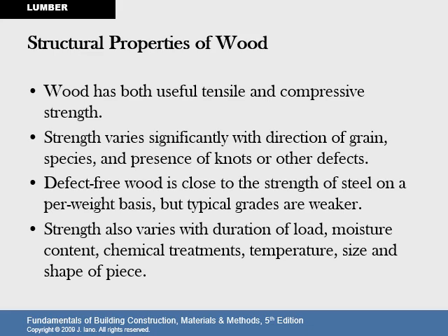Structural properties of wood. As you know, we're making wood studs, so wood has both useful tensile and compressive strength. The strength varies significantly with the direction of grain, species, and the presence of knots or other defects. Defect-free wood is close to the strength of steel on a per weight basis, but typical grades are weaker. Strength also varies with the duration of the load, moisture content, chemical treatments, temperature, size, and the shape of the piece.